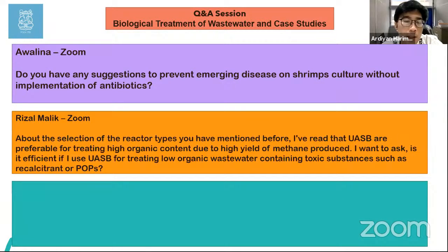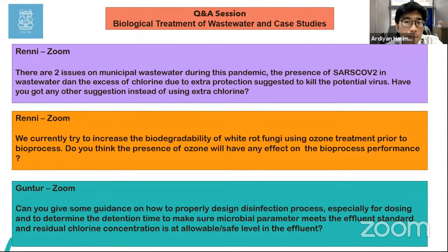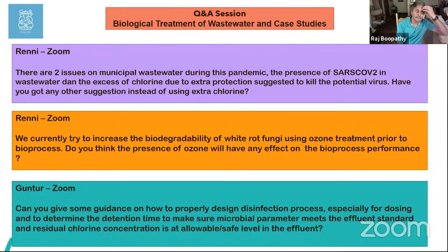And how about the detention time? Is there any best practice for chlorine? For disinfection in a wastewater system, they hold it in a tank, and it's basically just an hour at large scale. Around 1 hour, because of the amount of wastewater going through, you can't hold it long. It is a big volume of wastewater coming through. Okay, thank you, Prof.